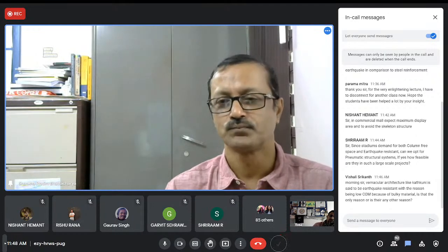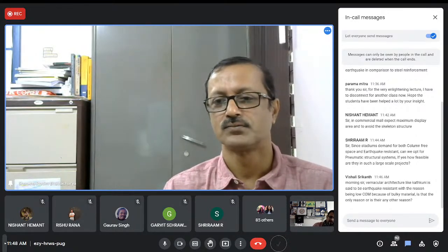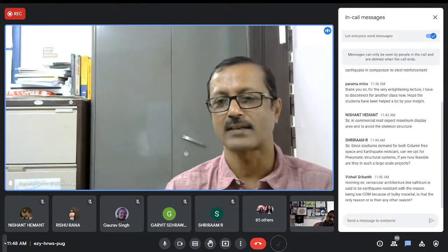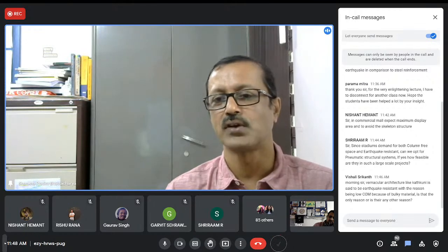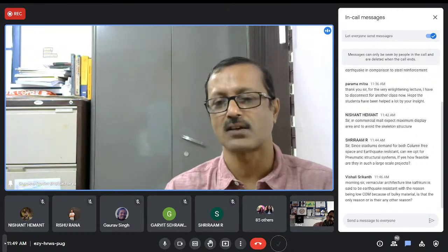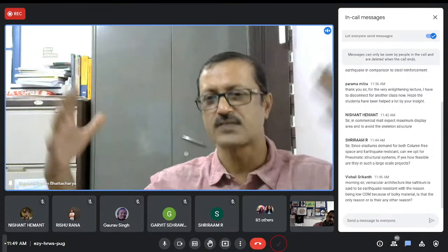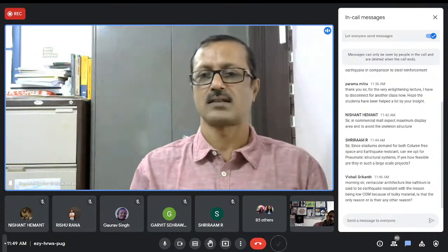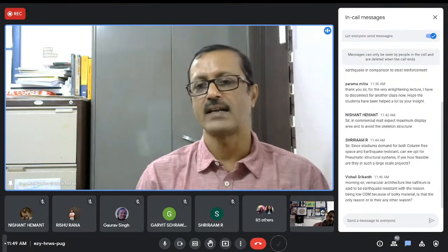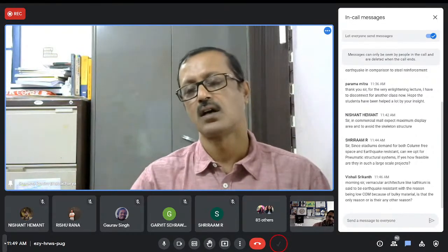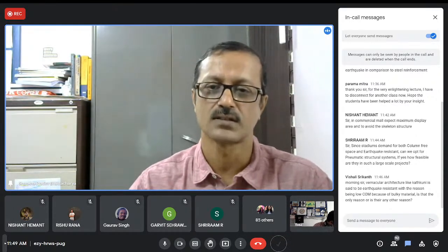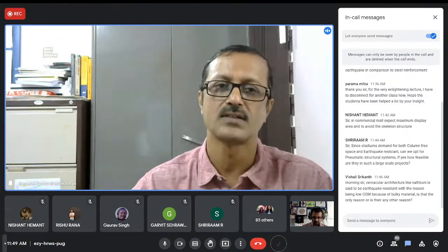So in the vernacular, the thick mass will help them as a thermal barrier. Plus, that will help in the consolidation of the center of mass and also the lightweight. In the other sense, the roof structure is very light. Maybe the wall structure is a little heavy, but the roof structure is very light, and the symmetrical additions and symmetrical layout of the building provide a very unique earthquake resistant solution.